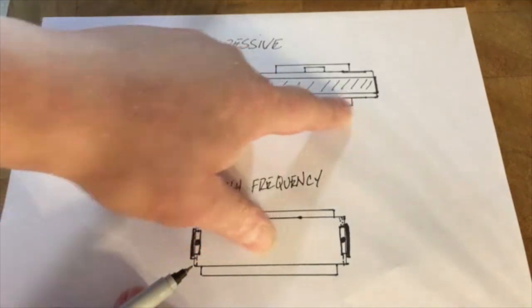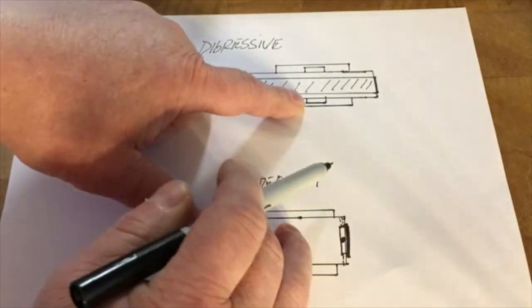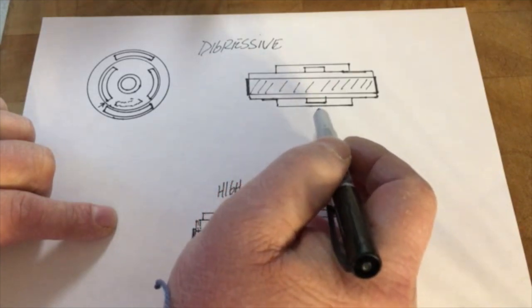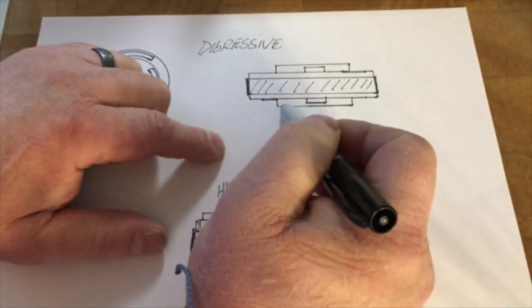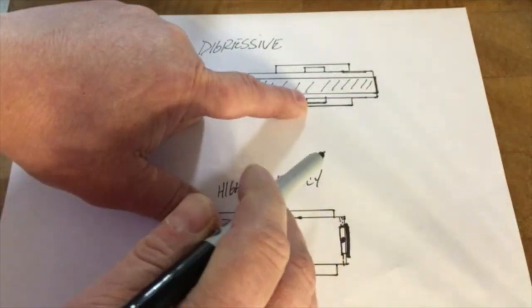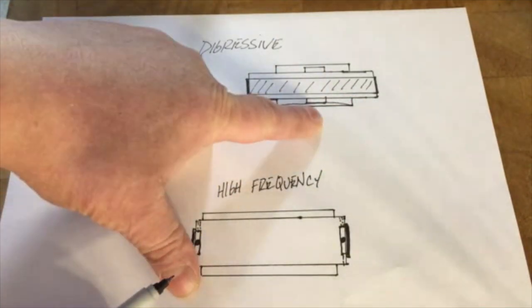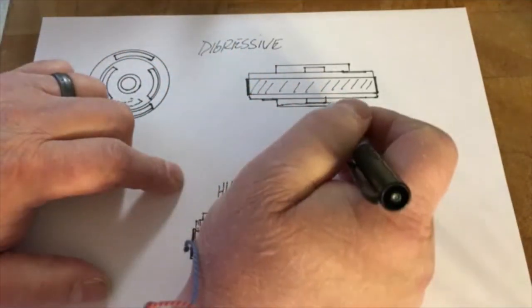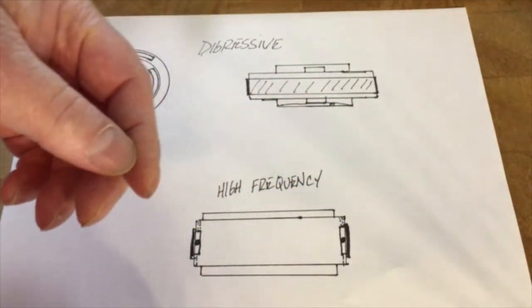to the cover plate. This is where your shock shaft goes in the side view here. It will actually bolt up, and when you put your cover plate on there and you bolt it all down, your cover plate will actually end up a little bit drooped, because this portion here is just slightly lower than your cover plate stops or your mounts. So this will preload your cover plate. And you stack all that up and you pinch it all together.